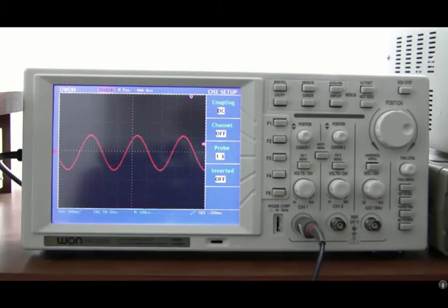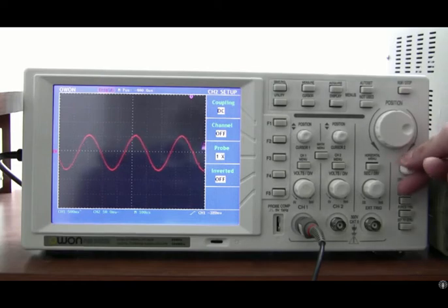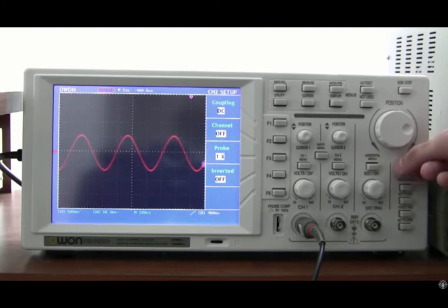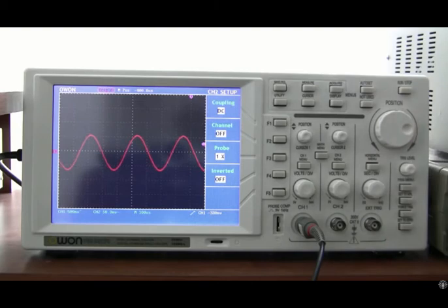The first thing I want to talk about is triggers. What is a trigger? A trigger is a voltage threshold that the signal has to reach before it gets displayed on screen. Now let me give you an example. By default, your oscilloscope is probably set to automatically trigger on whatever looks like an interesting waveform. This works really well for repetitive signals like the sinusoid I'm viewing here.